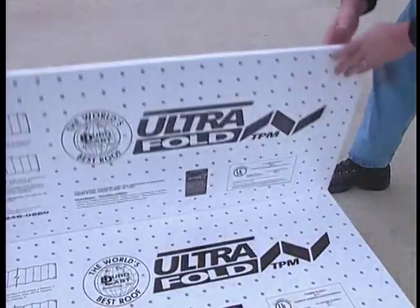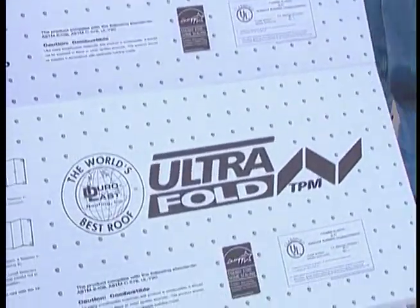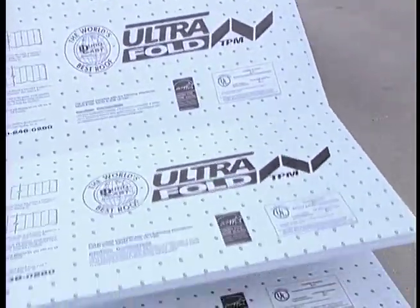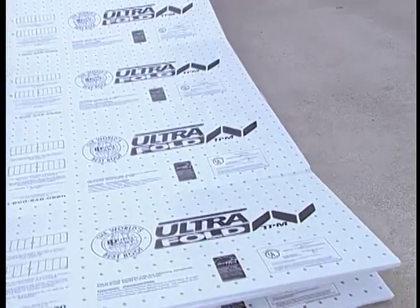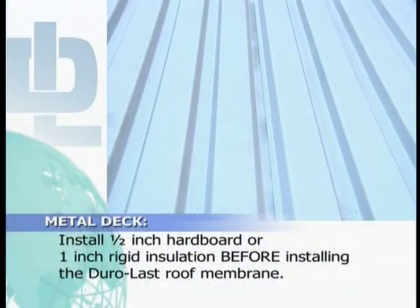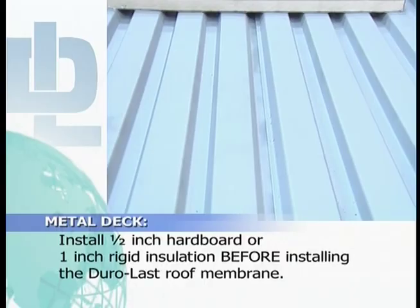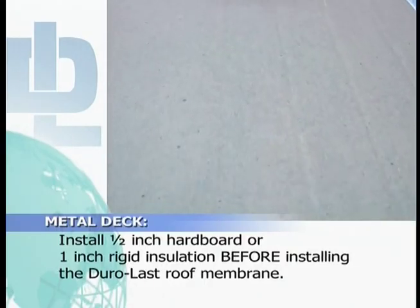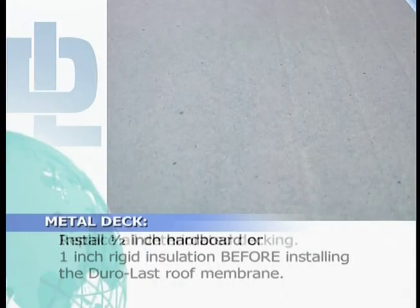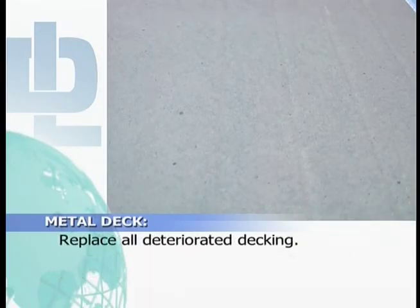Now, let's consider concrete decks. For new construction or replacement, concrete decks must be smooth and have no joints or cracks greater than 1/4 inch. If the concrete is not smooth troweled, it is required that you install a minimum 3/8 inch underlayment over the deck before installing the Duro-Last roof membrane. For new construction or replacement on a metal deck, you must install a 1/2 inch hardboard or 1 inch rigid insulation before installing the Duro-Last membrane and replace all deteriorated decking.